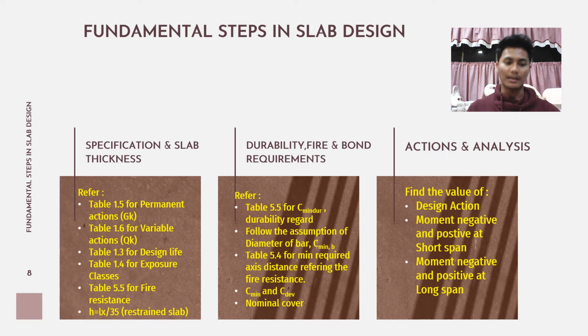And for the slab thickness, I choose h equal to Lx over 35 because it is a restrained slab.